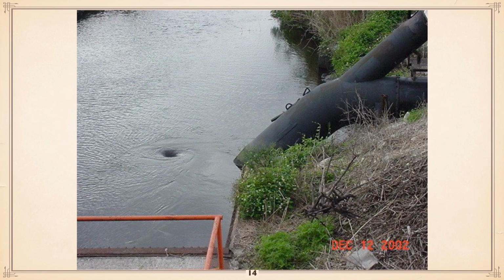This picture is kind of interesting. It's a drainage pump at an angle, and in fact, that column at the top right carries off the pump shaft, which is inside that. At the top, there's a motor with a belt drive to the shaft because these pumps run very slow. And you can see that a vortex has formed, and obviously air will very quickly be going into the pump.